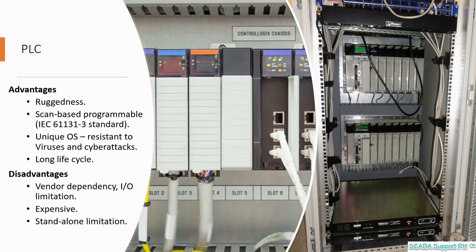However, IO options are limited since they're tied to the same manufacturer. PLCs can also be expensive, always coming at a higher cost than PC-based controllers. So scaling a PLC in the same way as an industrial PC is not always possible and could lead to additional cost and complexity.